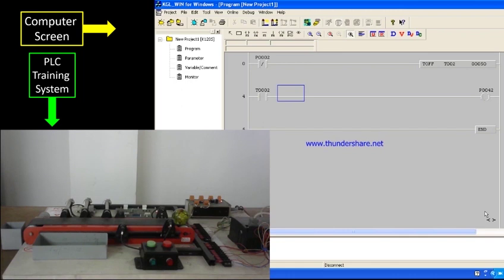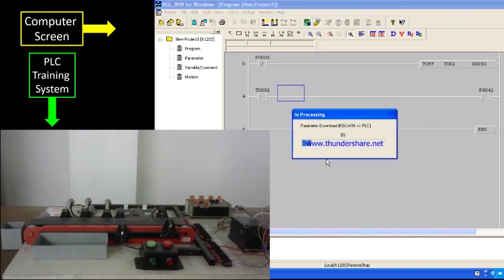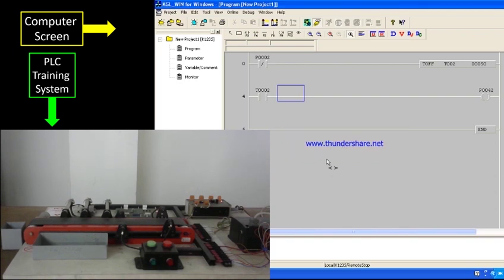Okay, so before that I need to illustrate one thing, how timer off acts. So we have seen that timer on needs continuous supply of energy to be activated, but we cannot have this same setup here, because if we give timer off a continuous supply of energy, it will not start counting down.